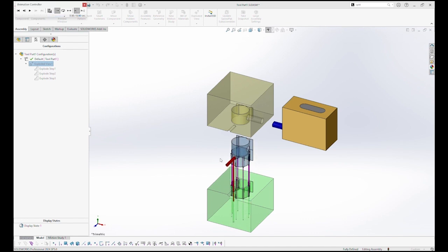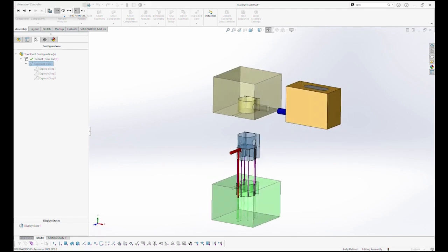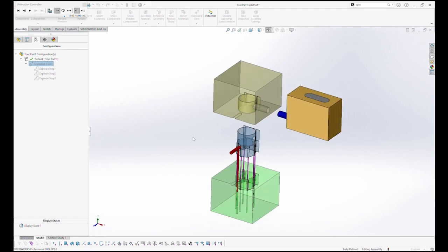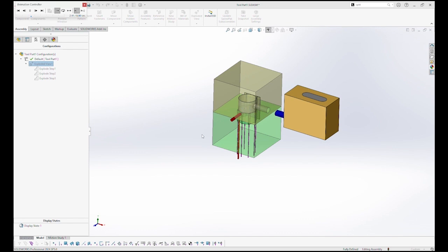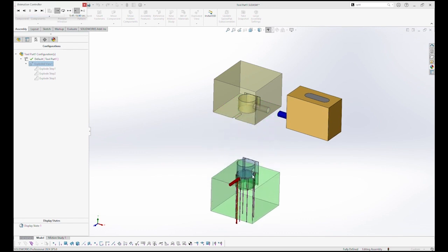And so now when you put the part and all the components that we had together with how this tool is going to operate, maybe the geometry of the part would make a little bit more sense. We'll run that through one more time. Slide's coming out, clearing the core for that hole. B side comes down, ejector pins lift the runner and the part out at the same time and then shear that gate off. So this runner and this part now are two totally separate components.